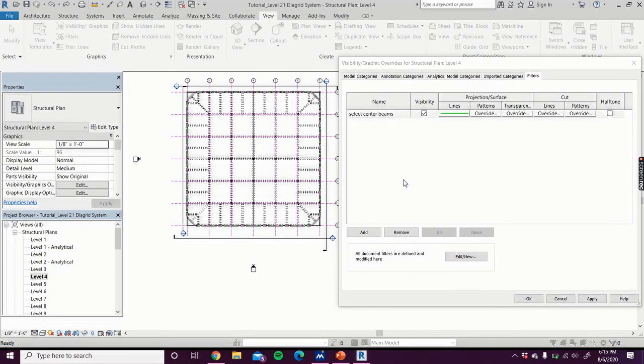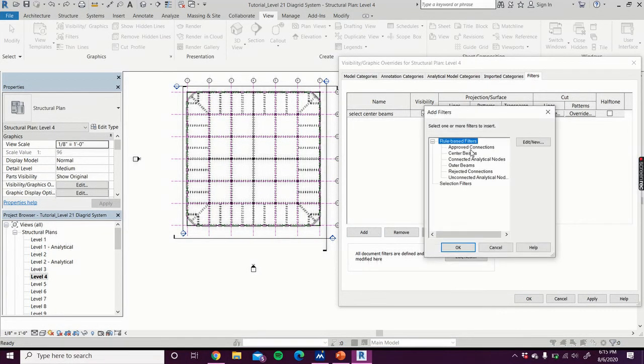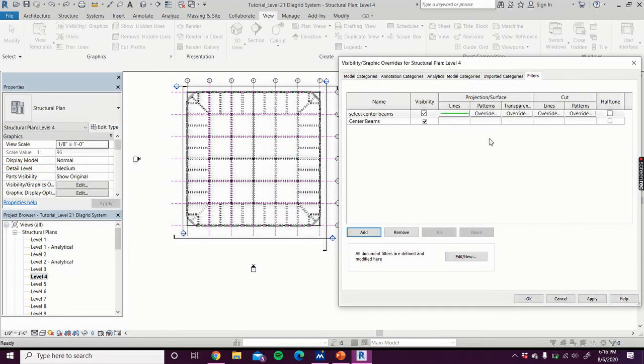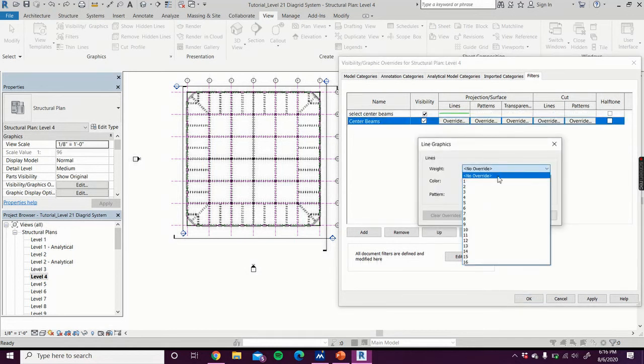That is why I prefer rule-based filters, because once you create a rule-based filter, no matter what type it is, no matter how you choose to filter it, it will show up on every single floor. You will have to change the filters and the appearance for every floor, but you shouldn't have to do that too often. But again, it is personal preference. If you want to select them, if you have whatever issues with the rule-based filters, that's fine.